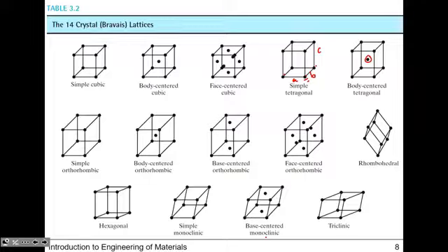And I should say all of these lattice sites are identical, okay? So if you put an atom down here, let's say, and I say, okay, it's body-centered cubic, I've just told you the entire symmetry of the system. That means if you understand the formalism, you know to translate the atoms this way, and 1, 1 over, and you also should know to put 1 at half, half, half of that unit cell. So that's based on the symmetry, okay?